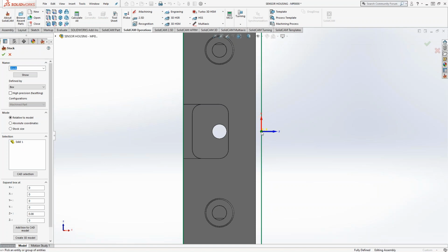Makes sense. Because the shops I used to work in were much poorer, so they didn't have probes. Yep. And we used those old school edge finders, the one that spins. And I always used to do the corner because obviously that's how you do it with those. But Kevin's right. A lot more modern machines, a lot more sophistication nowadays. Especially if you haven't seen, SolidCAM does have its own probe module as well. So that's probably why top center is a little more preferred nowadays, if not more accurate.